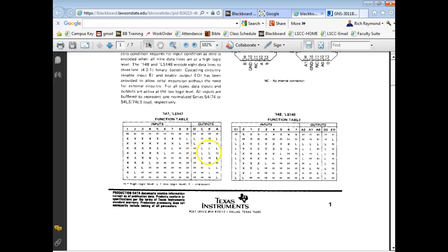But if I fed this into the 7447, it would display an 8, right? You understand? So what do we have to do? It tells us to put inverters between the outputs of the 74147 and the inputs to the 7447. So it's going to take me a second to wire that up. So y'all give me the pins, and I'll write them down here, and y'all can take a break.